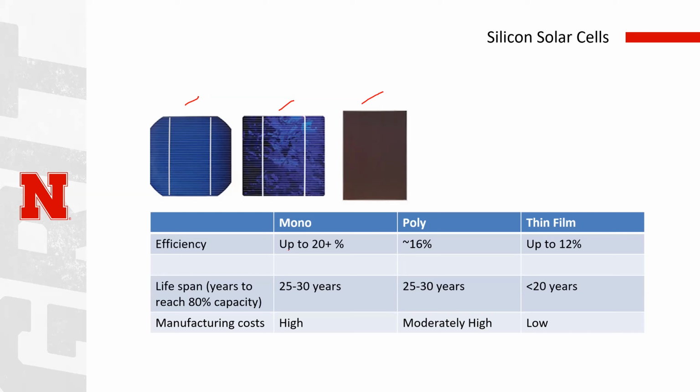Now, I know what some people have told me. They'll say, well, I want monocrystalline because it's the most efficient. And I say, well, yes, except it's more costly. And so sometimes we want to balance that. For example, if I'm putting these on a ground mount, I could put up 24 monocrystalline solar panels, or I could put up 28 polycrystalline solar panels, and maybe it costs less, right? So if space isn't really limited, that polycrystalline can be a good deal, and actually has decent efficiency.